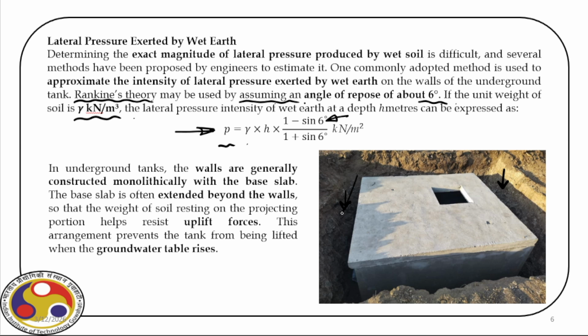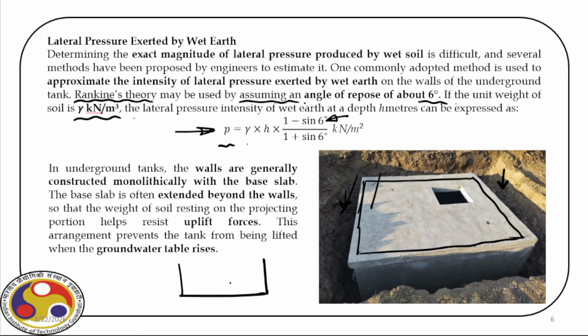then first a formwork is prepared and the concrete is poured for the construction of the wall at the 4 edges, if it is a rectangular tank, and for the time being, let us consider rectangular shape only. Before that, a soil is prepared at the bottom, and then a slab is cast that forms the base of the tank. Okay, so here is a soil bottom.